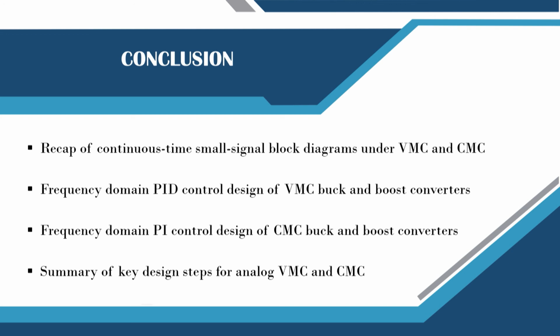And these are the primary steps before going to design digital control, because we will be using this frequency domain approach and we will incorporate the additional delay terms which will come due to the DPWM as well as the ADC delay, and then we can modify our design steps to design the digital voltage mode and current mode control, and that we will be discussing in the subsequent lecture.